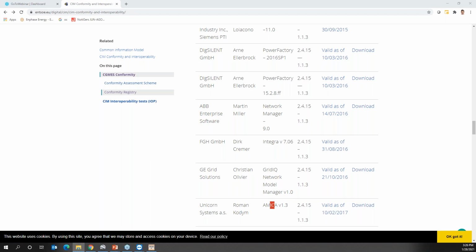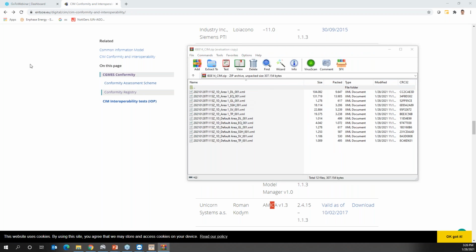So let me show you a little example with a network. I have here a CIM file. The CIM is based on the XML protocol. And for each kind of information, we have a specification. We can get information regarding the diagrams or the graphics, because they can be shared too. Or we can find information regarding the equipment. I mean, the parameters of the transformers, the transmission lines, and even the loads can be exchanged using the standard.